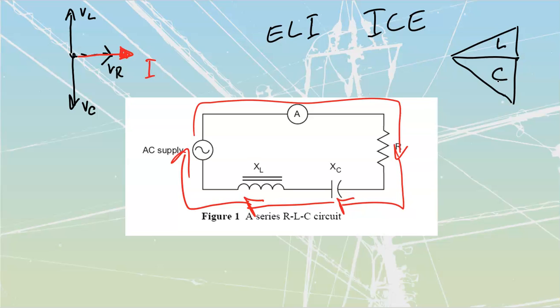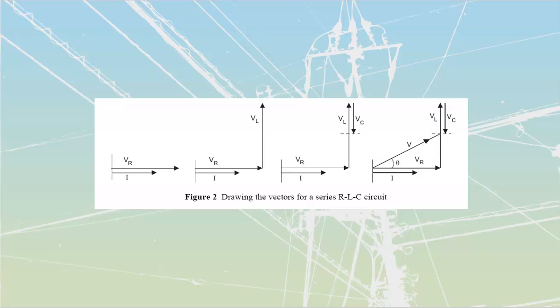When we take a look at the components that are inside of here, we should recognize as well that there could come a point where I could match my inductive triangle to my capacitive triangle. And then we're going to hit a special circumstance that we are going to call resonance. We'll deal with the resonance after we deal with just the simple utilization that we are going to have inside of here. The first thing that your binder goes through is a bunch of voltage vectors and the cancellation effect that we are going to have from the voltage on anything capacitive and anything that's inductive when we are dealing with a series circuit. Now, do note that this is a series circuit that we're dealing with. We can't use voltage triangles in parallel. We'll discover why later on, but it's very much a series-alone application.